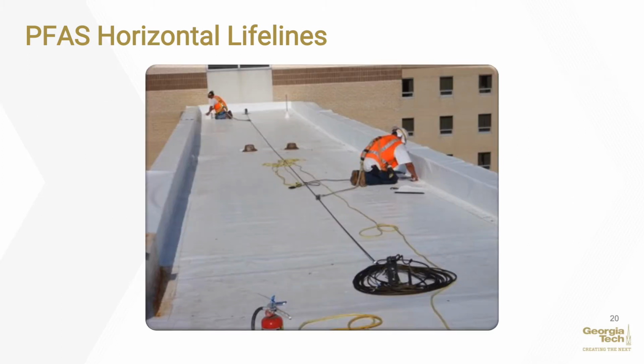Horizontal lifelines are to be designed, installed, and used under the supervision of a qualified person and as part of a complete personal fall arrest system which maintains a safety factor of at least 2. Horizontal lifelines must meet the 5,000 pound strength requirement per employee anchored to the system. Caution: guardrail systems and horizontal lifeline systems are not the same thing. Guardrails must withstand only a 200-pound force, and tying off to a guardrail system can be deadly.